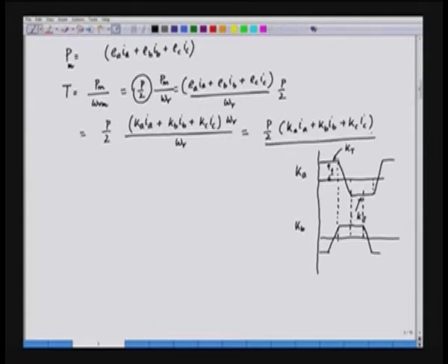Now, when we get the torque, we can get back the speed by having the electromechanical equation. So, the electromechanical equation is the inertial torque d omega r by dt into J by P by 2. We neglect for simplicity the viscous friction, but the viscous friction will also come here, B by P by 2 into omega r, plus the load torque is equal to the motor torque.